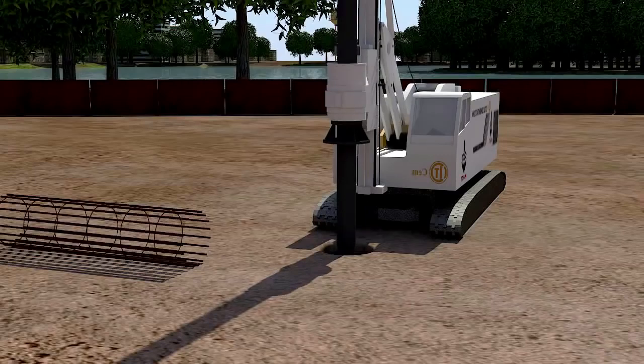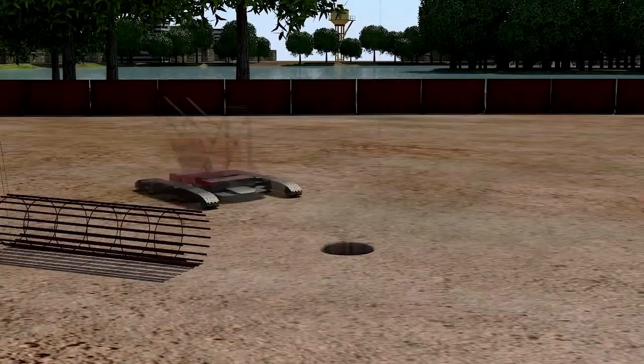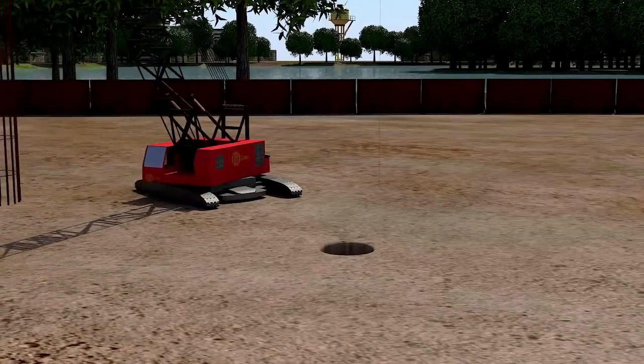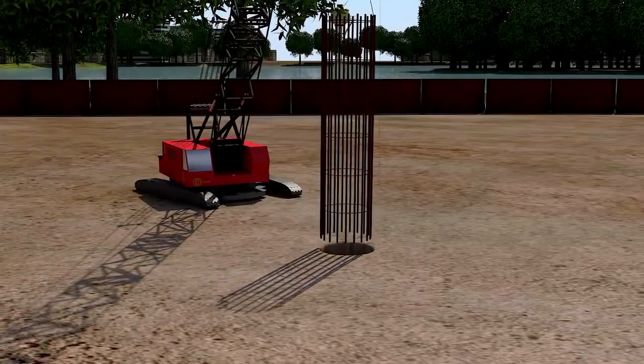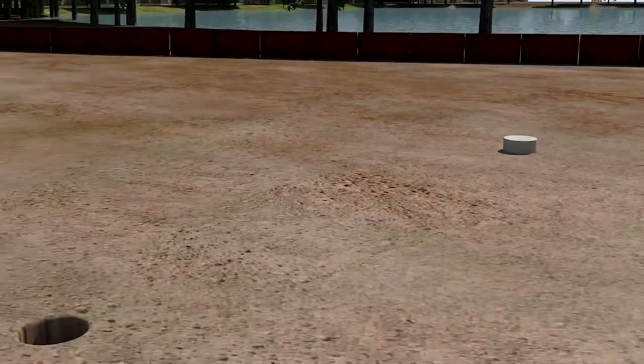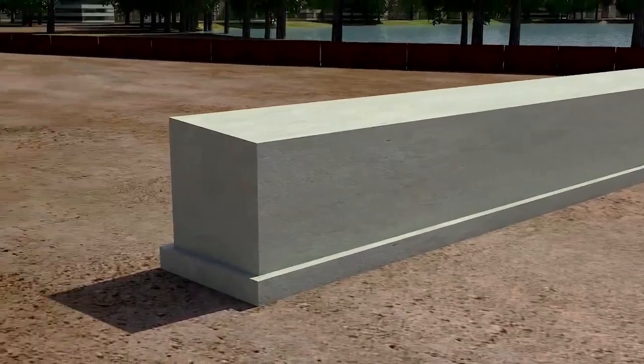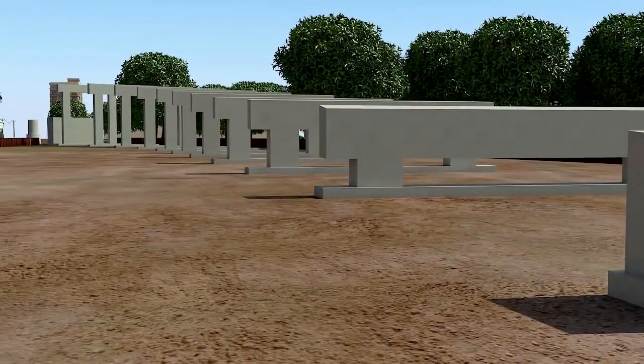To create the elevated viaduct, piles are constructed by boring holes, placing the rebar cage and pouring concrete. Pile cap is created and then piers are constructed over the pile cap. Pier constructions of different heights are done to extend the ramp above the ground to the desired height.